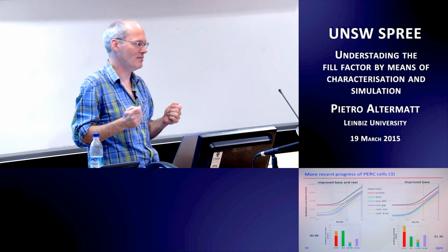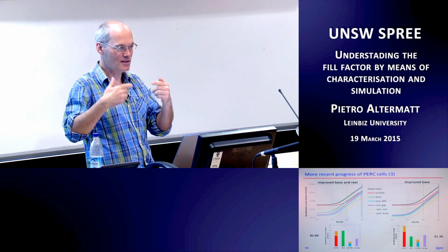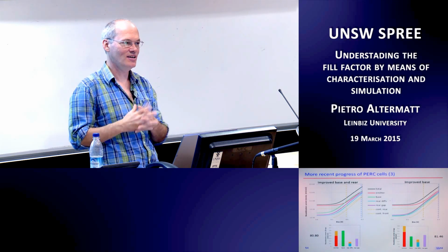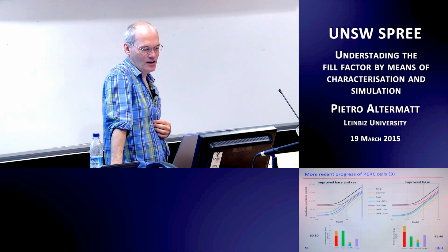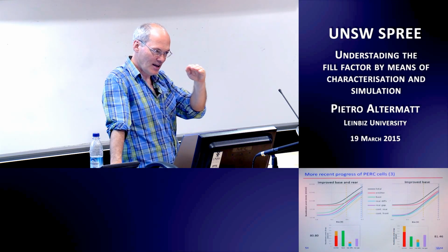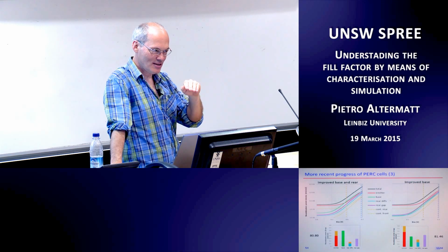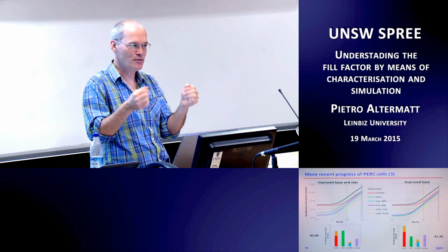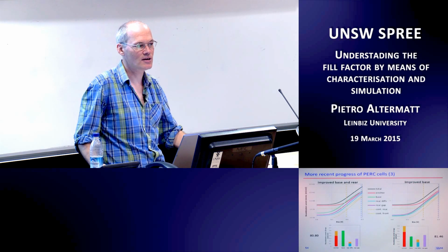I mean, there are people that say we shouldn't even call it J naught. I think we should call it J naught. We should only make a distinction of how I operate locally such a diffusion, instead of thinking that J naught is all kind of wrong. And when you look at such an emitter, that actually also leads to a different ideality factor. You know what I mean? So it's not only the base, a quite high resistivity emitter can also have such effects, just by recombination, apart from the resistive effect.